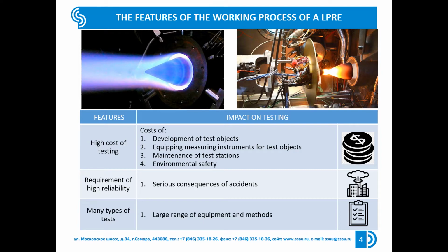The LPRE tests are usually multifactorial, meaning they take into account the influence of many factors. Tests are conducted in large numbers to accurately assess the reliability of a liquid rocket engine. Sometimes it is necessary to conduct tests in boosted and loaded modes, which are characterized by increased, compared to nominal mode, component flow rates, extreme or above gas saturation values, a wide range of inlet pressures and other external conditions.